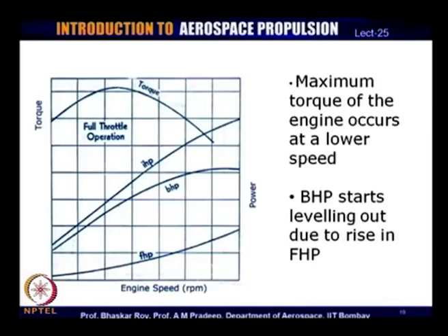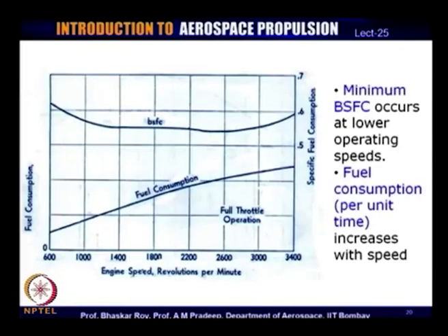This is found out from engine estimation before the engine is actually installed. If we look at BSFC, we have seen it is one of the most important parameters of engine operation. It is indicative of the efficiency of the engine. However, in this graph we see that BSFC and the total fuel consumption are two slightly different issues.